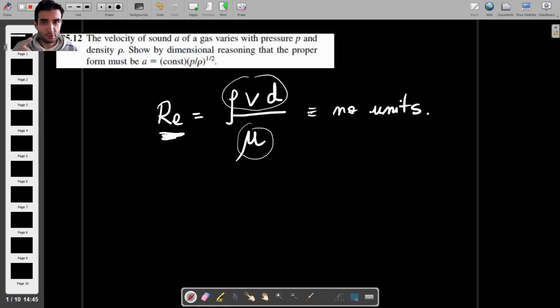And if you know the two Reynolds numbers are the same, then you can find things like, okay, what speed should my aircraft fly at? Or rather, what speed should I do the testing in the wind tunnel? Okay, or what should be the size of the model? That's the diameter, for example, or the chord length or anything like that. So yeah, that's the basic idea.